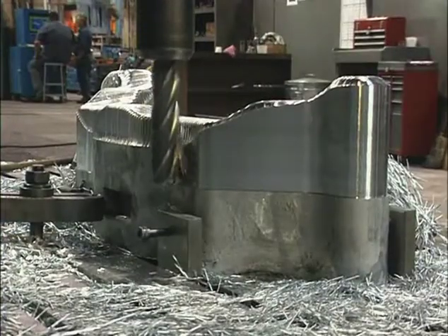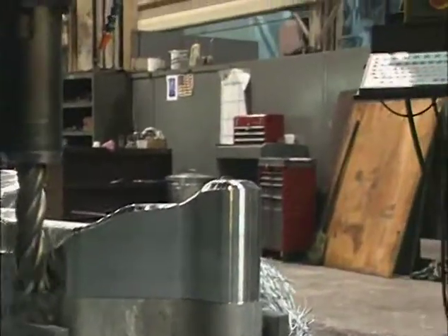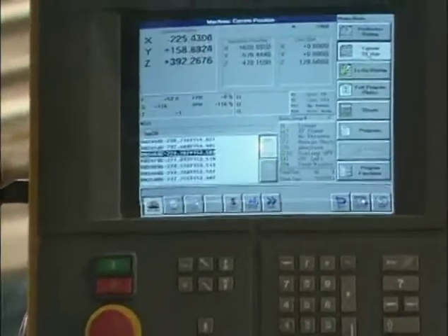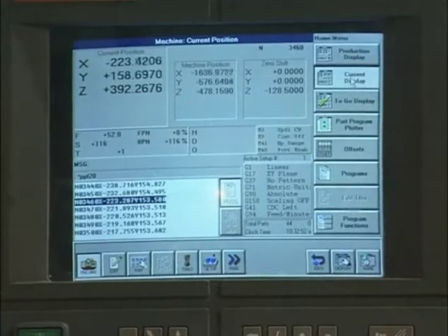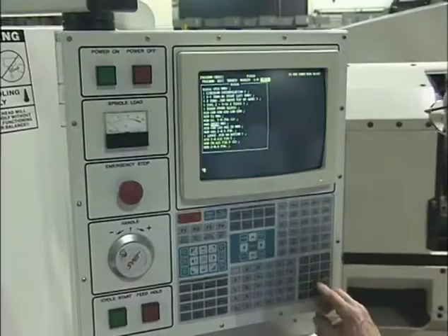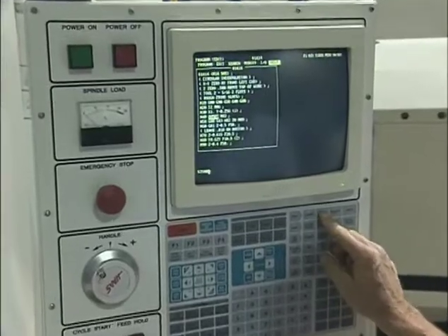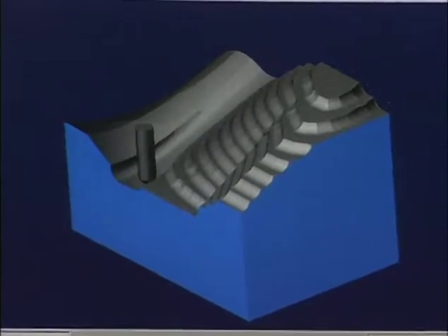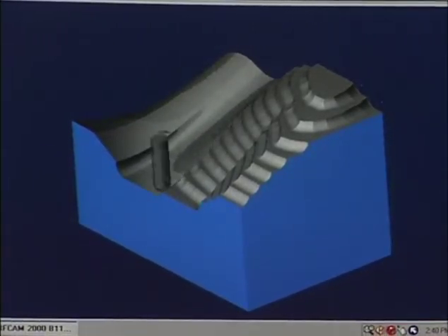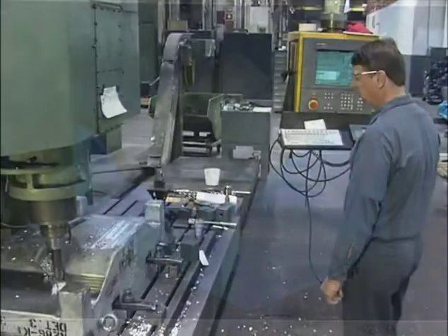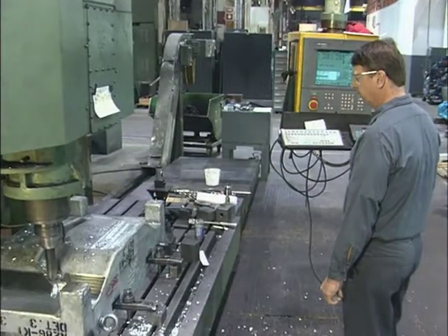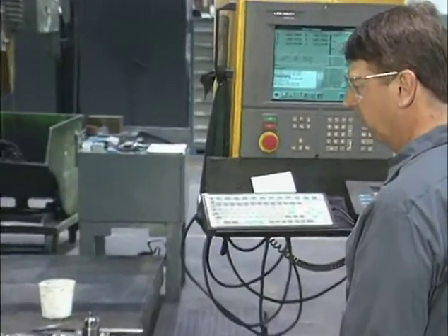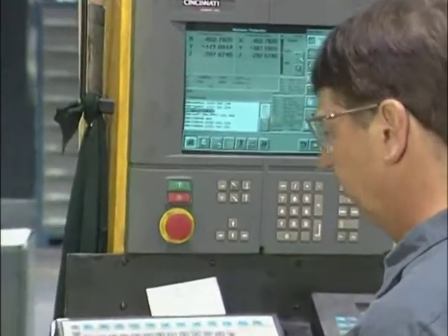All computer numerically controlled machining begins with a part program. A part program consists of sequential instructions or coded commands that direct the machining of the part. Part programs are primarily generated by either manual programming of commands or more commonly by the use of computer-aided part programming systems. To understand how computer numerical programming works first requires a basic understanding of key computer numerical control principles.